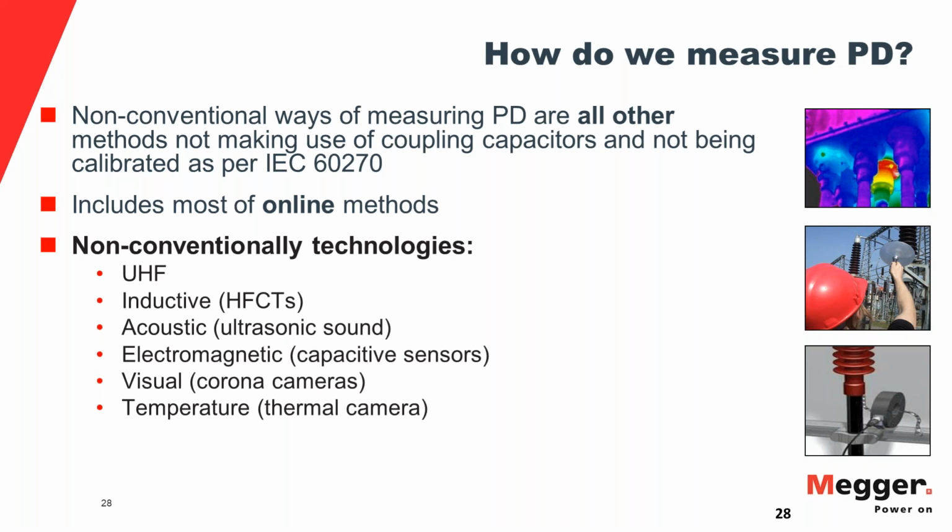You cannot calibrate the circuit because you rely on operating voltage, so it's kind of a warning system. You gain yourself a little bit of time just before the catastrophic failure to take action, but you don't really see the condition coming because you cannot vary the system voltage to 1.7 times or something like that to see if a condition is coming up and growing.